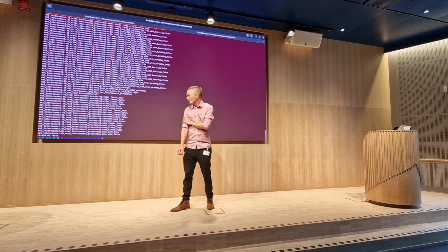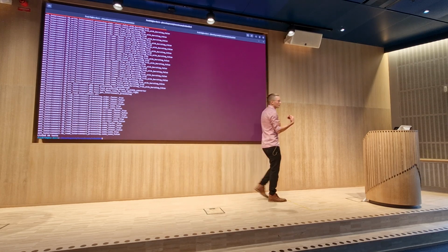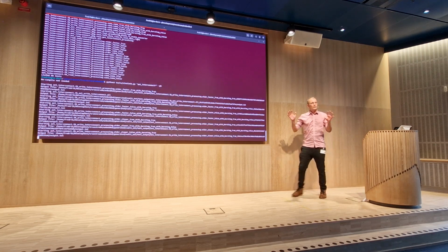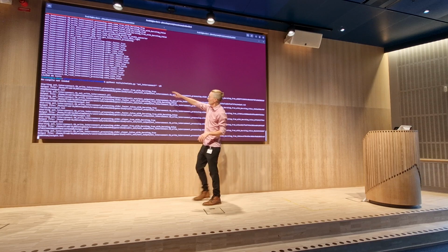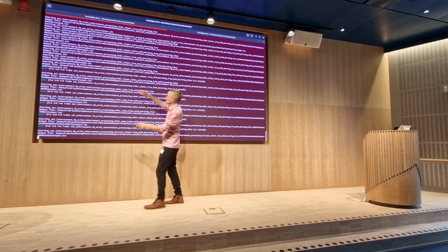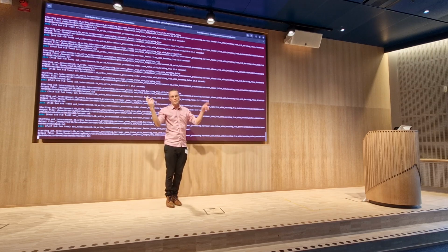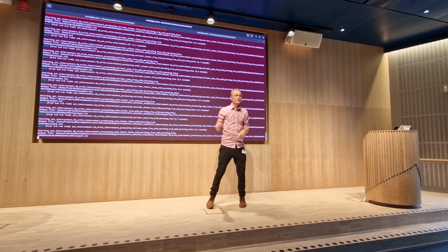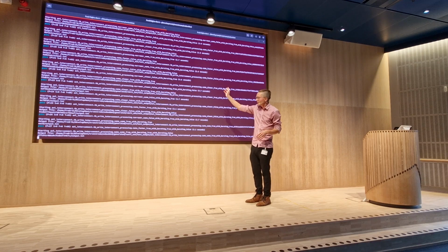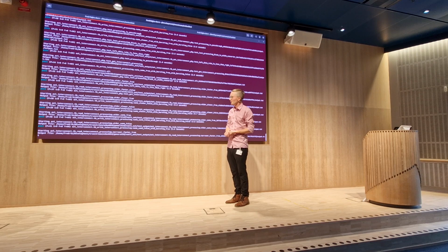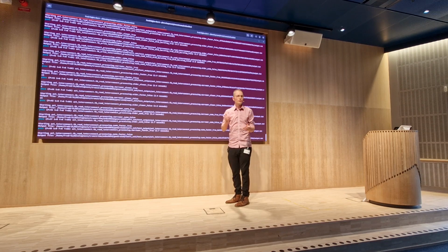tests? And if we were to run them one at a time, this demo would take too long. So instead we use 8 threads for doing that. And now the VUnit test runner is working. We gave it 8 threads on this laptop, and it can start 8 tests simultaneously. As soon as one finishes, the next one starts. And we get the test results on the fly, and soon, at the end, we're going to get a nice summary of all the tests.